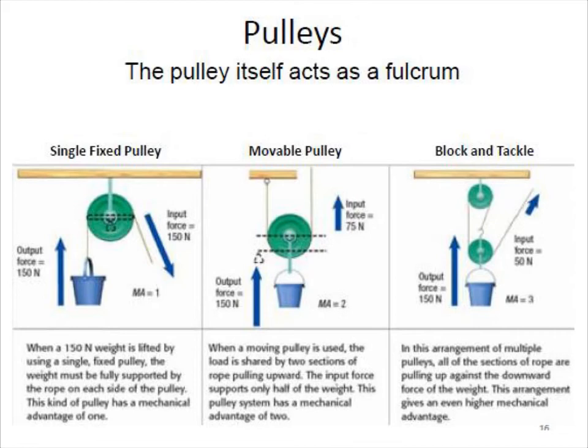A fixed pulley has an axle attached to a supporting structure that does not translate and changes the direction of a force. A movable pulley has an axle and a movable block and is supported by two parts of the same rope. A movable pulley can translate and move the rope when it is pulled. Pulleys are usually used in combination, as you see in figure 3.